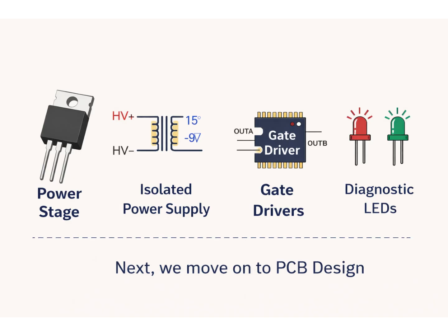With this, we come to the end of the circuit design part of the inverter. In this section, we have covered the power stage, the gate driver circuits, the isolated power supply generation, the control interfaces, and the diagnostic LED indicators used to monitor the switching state of the IGBTs. Each block was designed with safety, noise immunity, thermal reliability, and practical testing in mind.